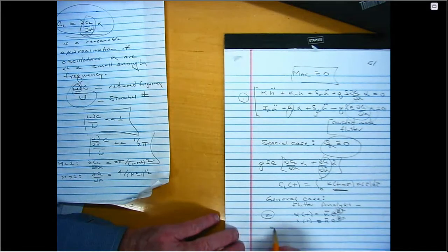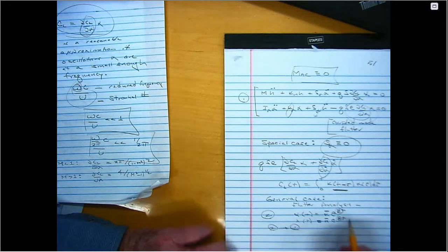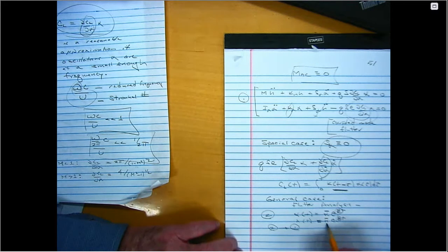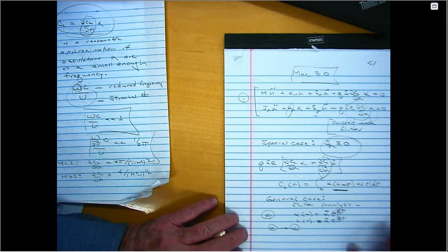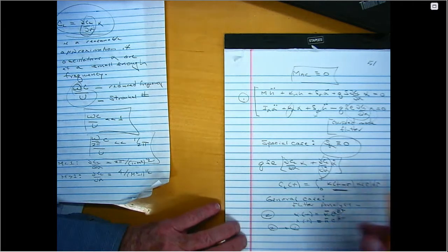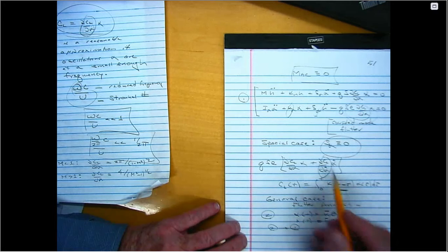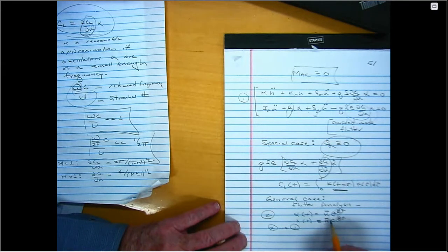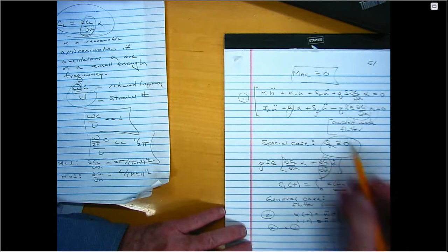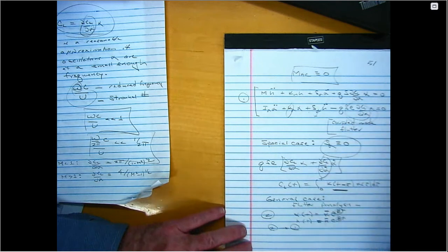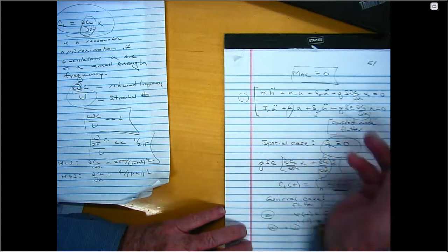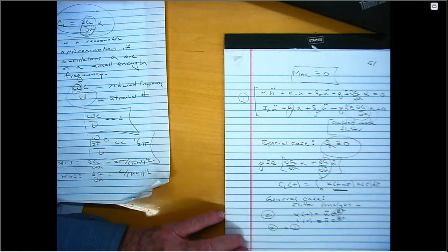So now if I put 2 into 1, I'm going to get some common factors, alpha bar, H bar. I'll get some common factors, e to the beta t. I can cancel out all these beta t's. And therefore, I can write these as linear algebraic equations. These differential equations, once I assume the solution of this form, will become linear algebraic equations for H bar and alpha bar, right? Where the coefficients will involve Q and beta and lots of other things. But the principal thing I want to know is how beta varies with Q, for given values of mass. So what does that look like?